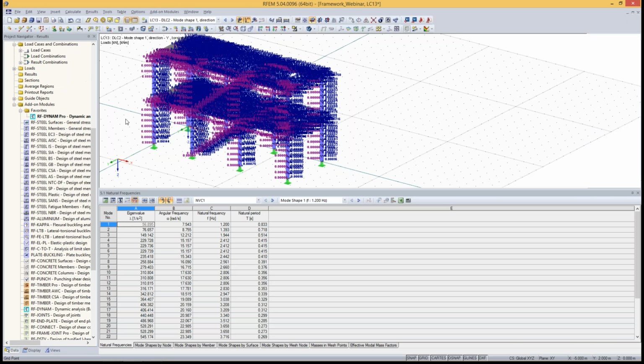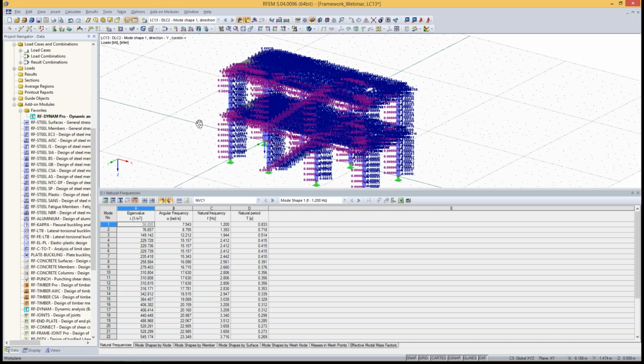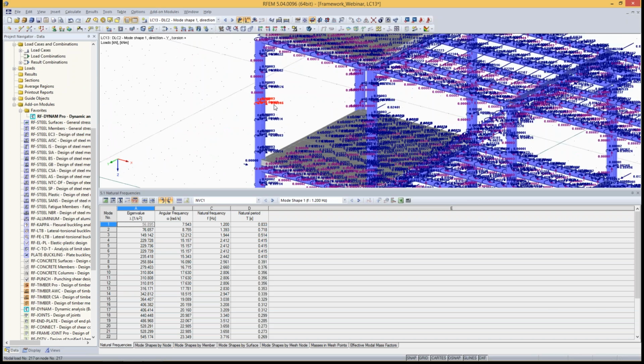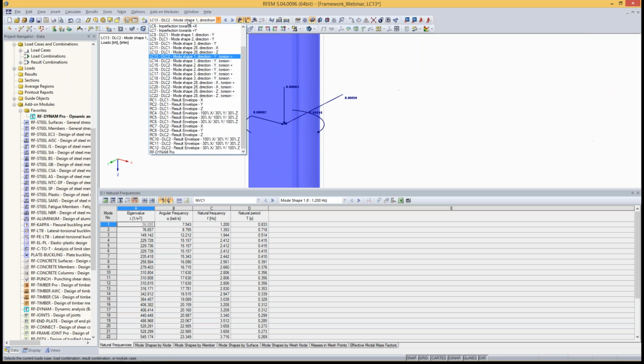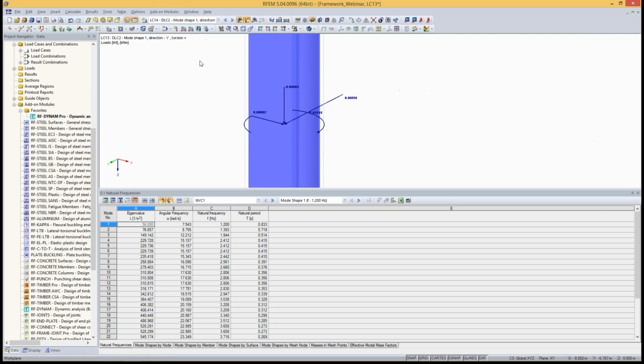And let's just have a look at it. It looks terrible if you don't zoom in. You have so many loads, but if you zoom in, you see the applied equivalent loads in all 3 directions and you see the torsional moment, and this is the torsion plus case. And if I switch to the other case, the only thing that changes is the direction of the torsional moment. So the number stays the same, and the equivalent loads stay the same as well.